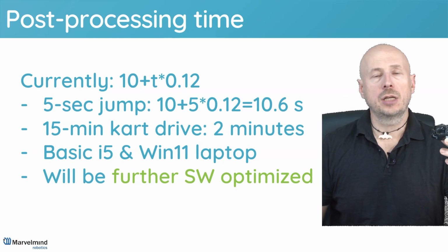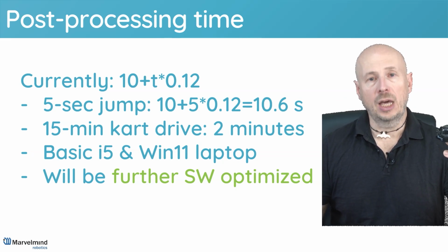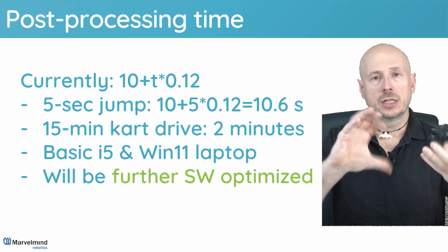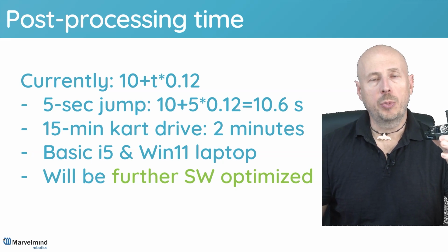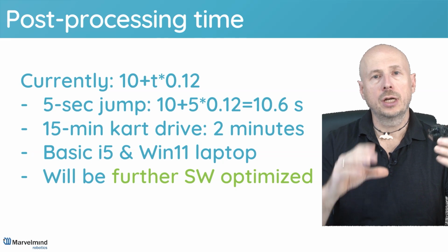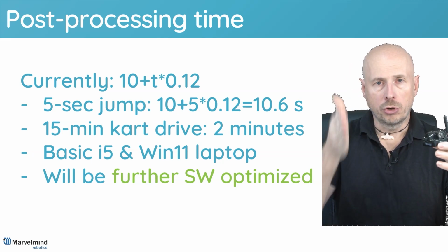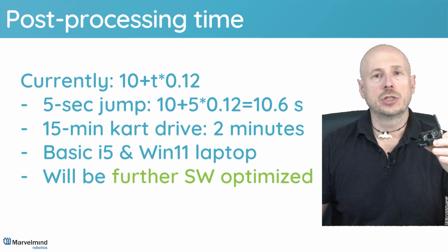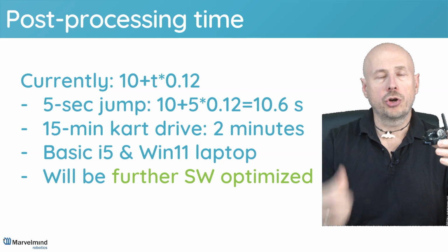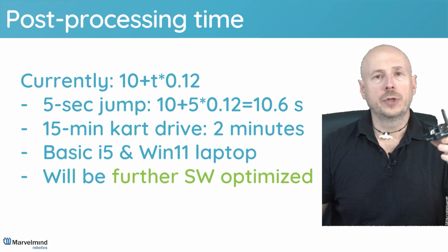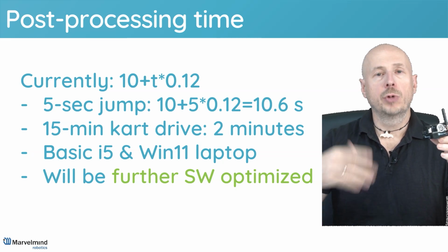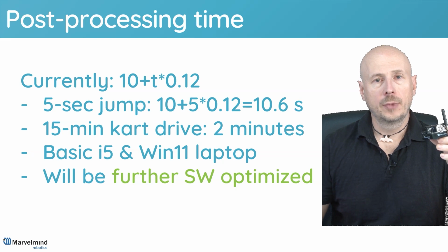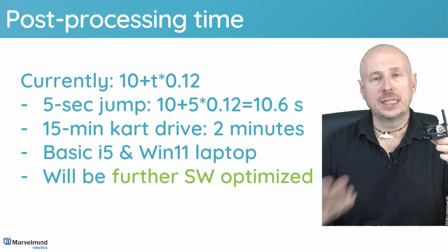And these streams of data, they have, of course, timestamps. So this is why the sensor fusion algorithm is capable to combine the ultrasound data and IMU data, of course, with proper timing, and thus, after the sensor fusion processing, it's able to return perfect locations and 100 Hertz update rate. But it's post-processing, so it takes time.